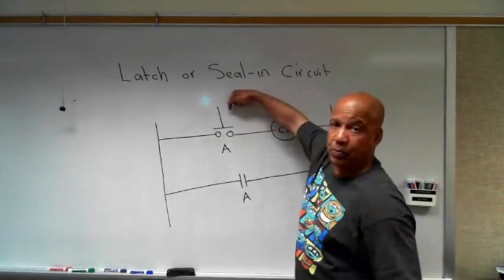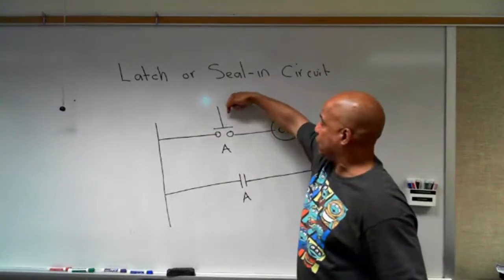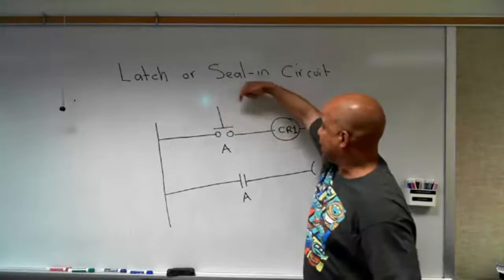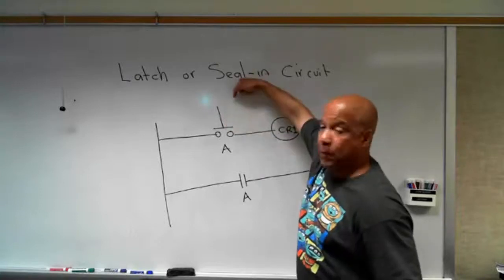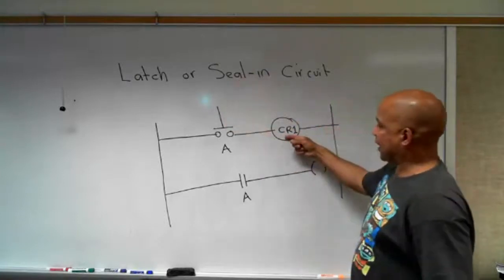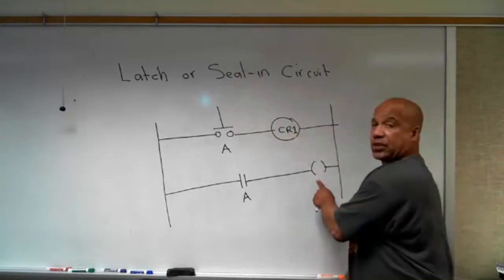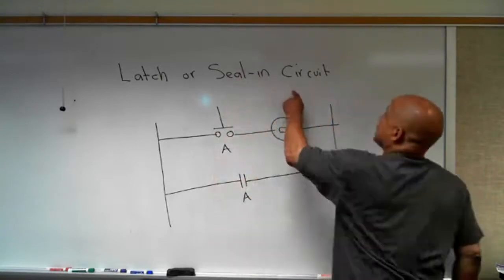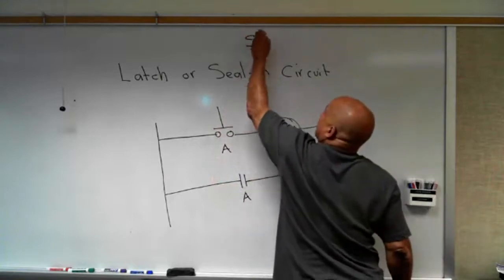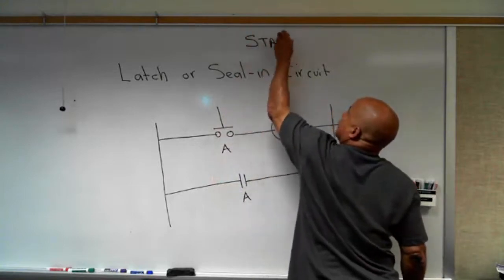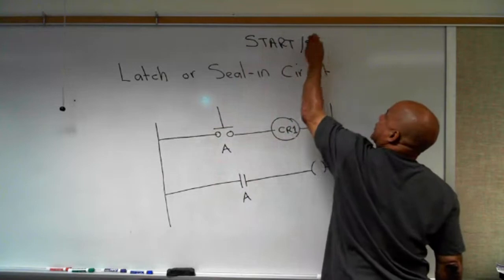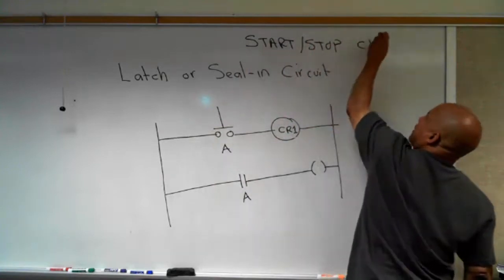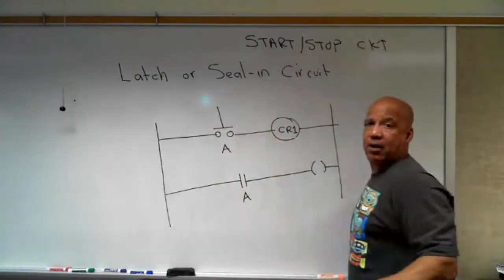Well, this is a normally open button, so it's only going to activate this while I have it pushed down. When I open that back up, then it's going to interrupt power to this. It's going to turn this off. What I want to do is have a start button. This is a start-stop circuit. That's what this seal-in stuff is about.